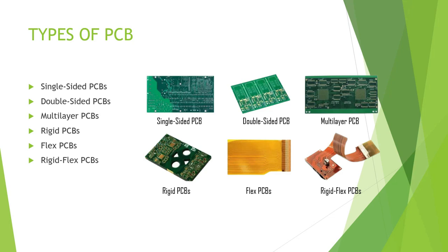And the double-sided PCB, as the name implies, is a sandwich. The two copper layers are available at top and bottom, and the center part is called the core or substrate. The PCB material is FR4 or some other glass epoxy.